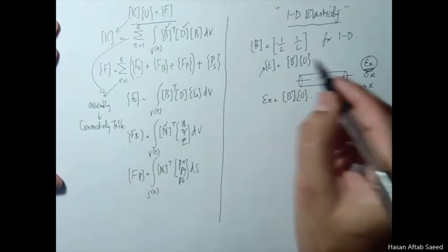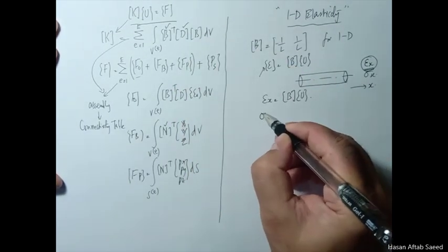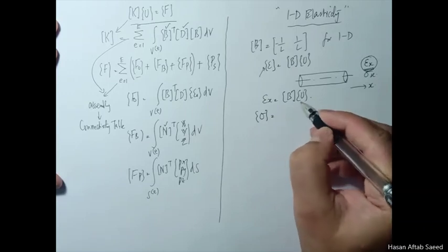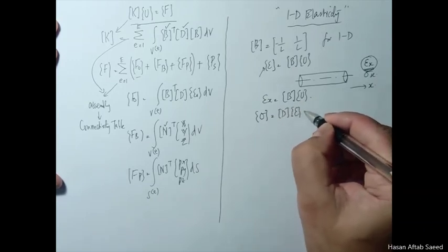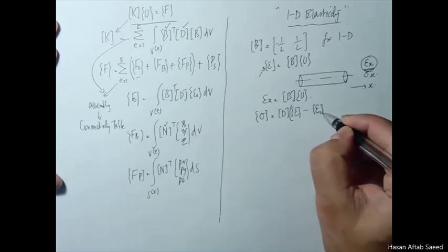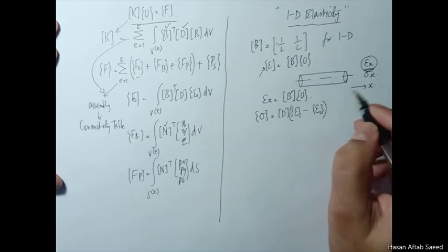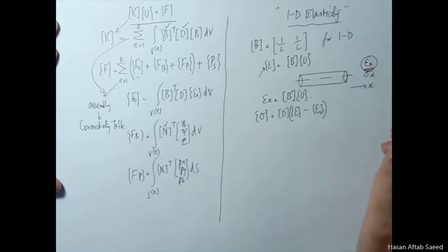Similarly, when we talk about this D matrix, we know that generally the expression for Hooke's law is something like this, and if we subtract the effects of initial strain as we must, then this is the shape of Hooke's law.